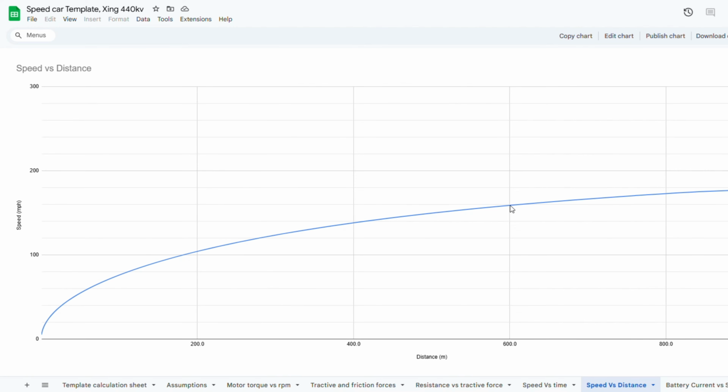It's something to bear in mind that with a lower kV motor, you might think it'll have more torque, but that's only if you can put the same current through it as a high kV motor, which you probably can't because it's going to have more turns on it, and so because of that they tend to have to use thinner wire which has a lower current limit.